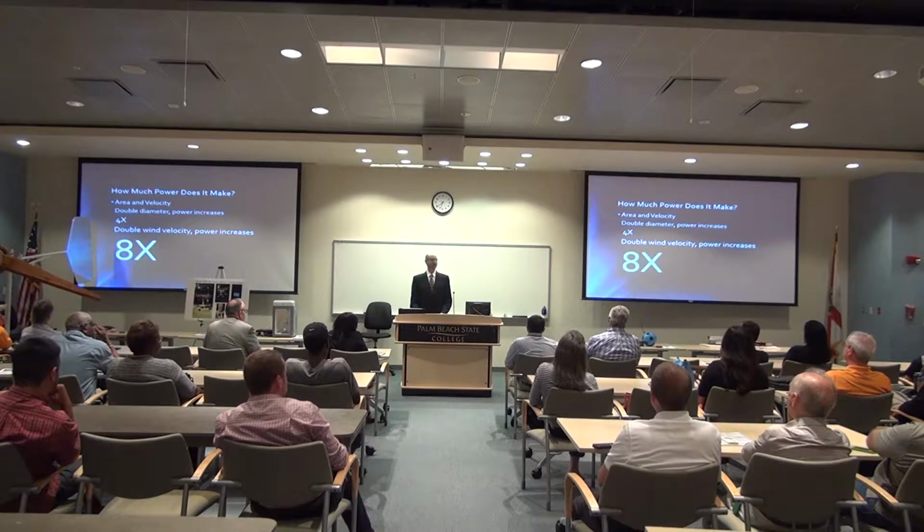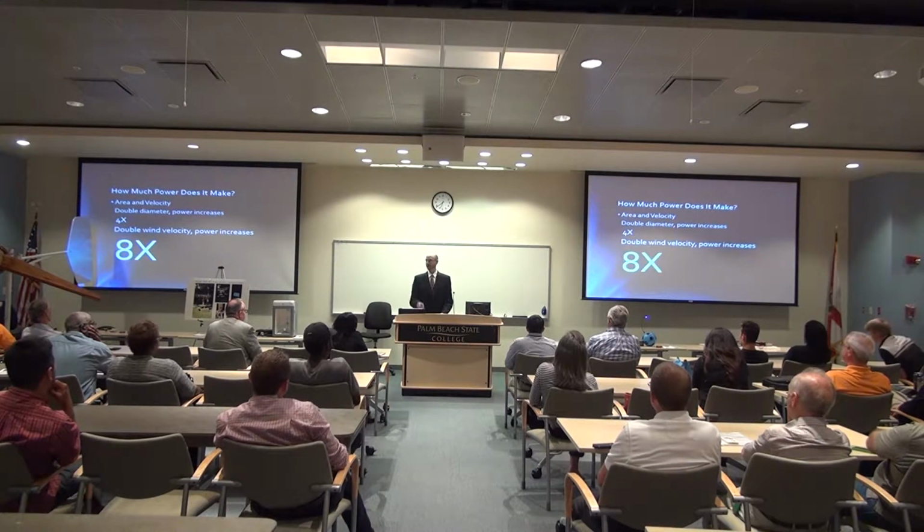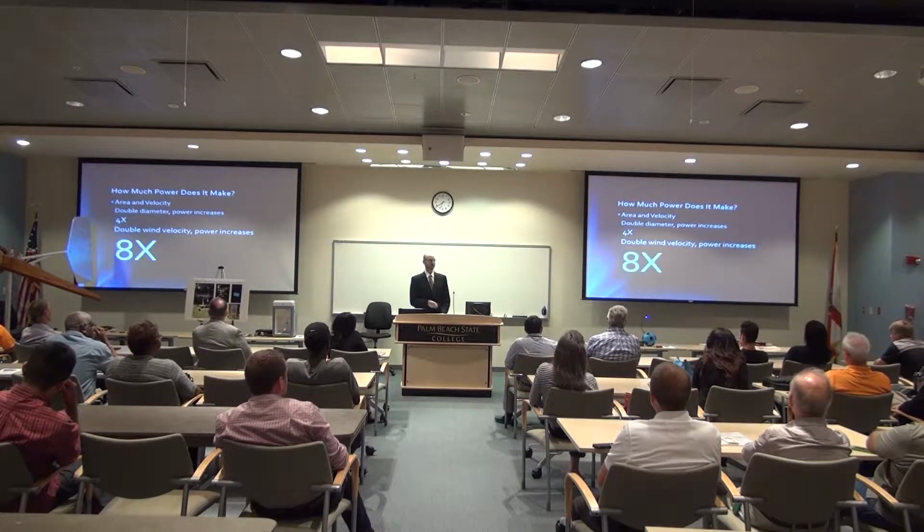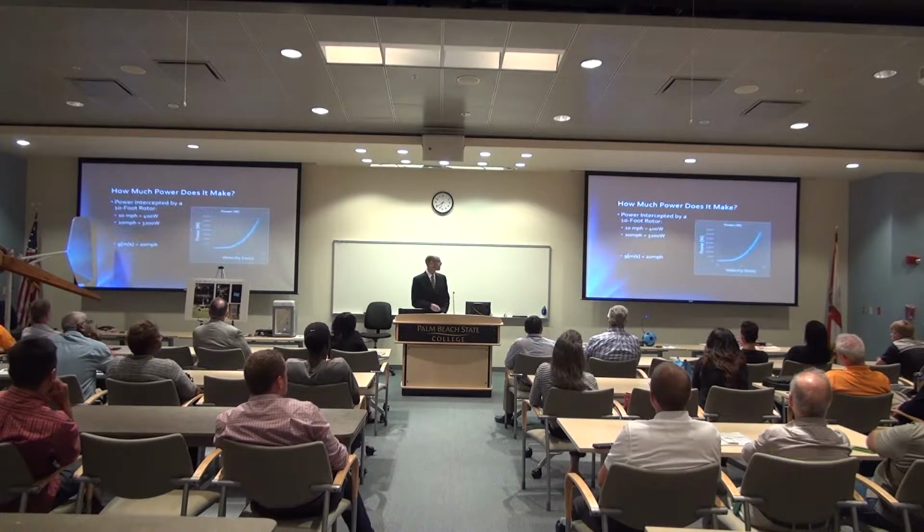But if you can't move out to California and you're stuck in an eastern state, you can actually influence the velocity of the wind that your turbine experiences by changing the height of your turbine. So by putting your turbine on a taller tower, due to an effect called wind shear, your wind speed increases with the height of your turbine. So let's look at how much power is actually available in the wind. So this is a curve for how much power a 10-foot diameter rotor can intercept.